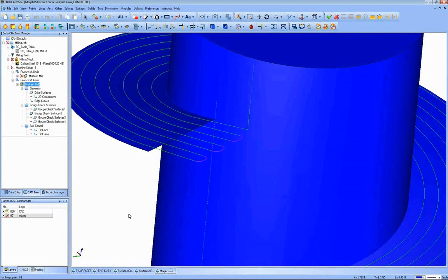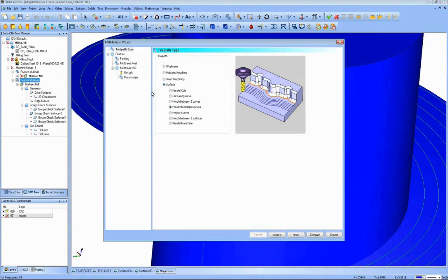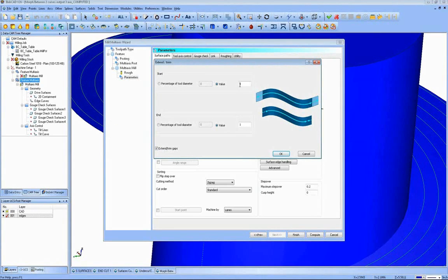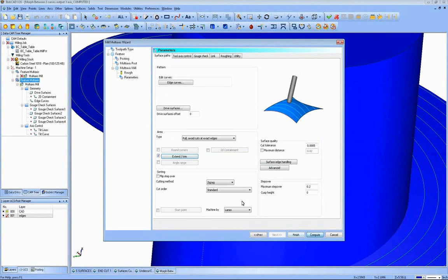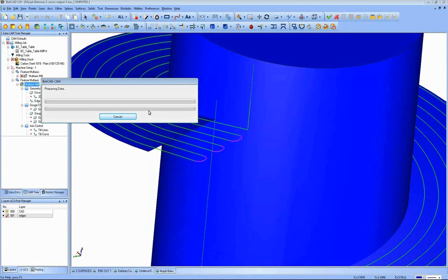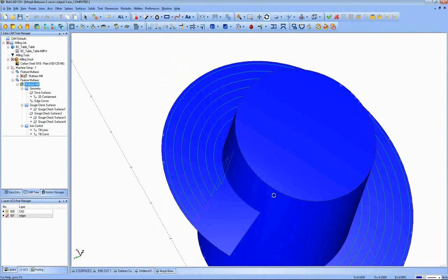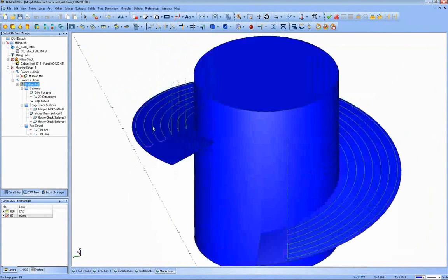Again, if you want to stop it short on a surface, go to our extend and trim, minuses in here instead of pluses, and this should go back in that way 1 inch, as you can see.